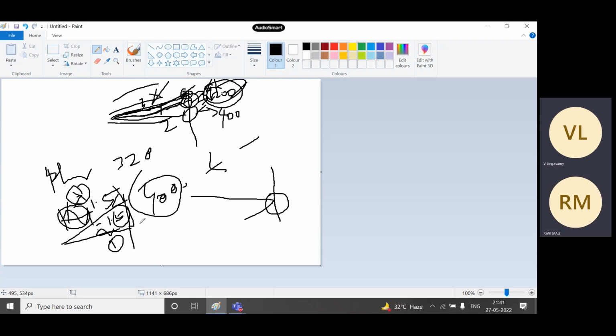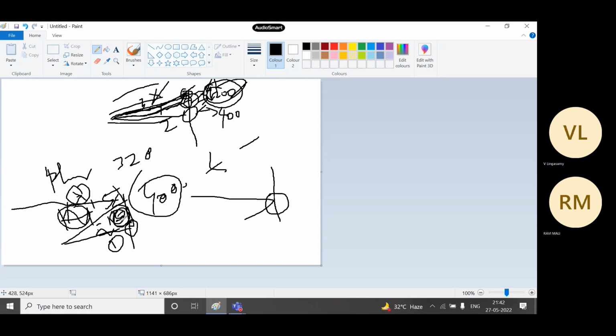What I have to do is introduce a delay over here in order to get that compensated. While reflecting back, this one has to go as it is, and here I have to introduce a 0.5 second delay. In other words, we can say phase. So in a reflector, you should be very careful about the terms delay, phase, compensation, and matching. Everything is closely related, basically.